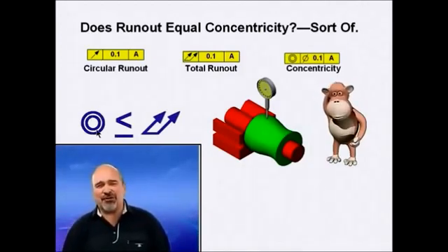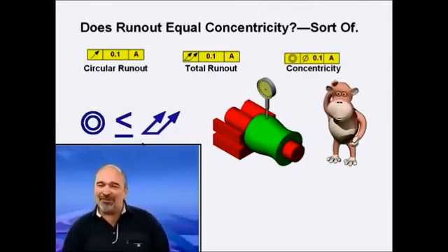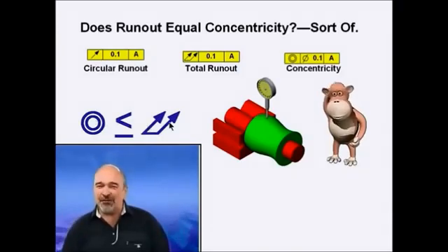But why not just forget about concentricity and use runout? It's easier to verify and also controls the form. My philosophy, when in doubt, use runout.